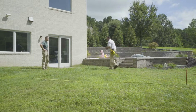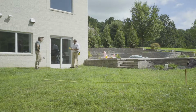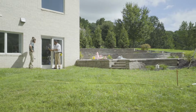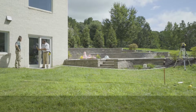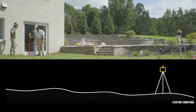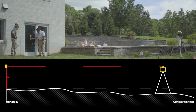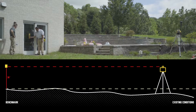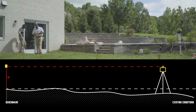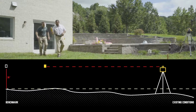The best and most accurate system is to use a laser level. We have our tripod set up. This is a handheld receiver. Once I powered it on, I can hold down the benchmark button and it will project the laser. You can see it down there on that threshold. I see it right now. And it will get me a benchmark. Once that's done, I set it, and now I can use my points right here, and I can move anywhere along this site. Very cool.